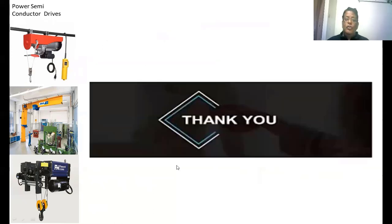Before closing this class, let me summarize the points we have discussed. We have seen what is meant by first quadrant operation. First quadrant operation is simply where the output voltage and current are positive. The load power becomes positive, so the motor will be rotating in one direction. Next, we have seen the operation of the circuit and waveform of a DC to DC converter. This converter is also nothing but a step down chopper. We have derived the expression of the average output voltage, that is V naught equal to alpha into Vdc.